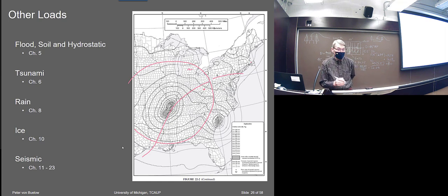Anyway, there probably wasn't a lot, and what there was, well, it would have been newer. Now I know, like where I live in Dexter, it's all masonry. It's all unreinforced masonry, and it's all like 150-year-old unreinforced masonry. So that you can almost kind of chip the mortar out with your finger. Some of it's been tuck pointed and repaired, okay, but it's still probably not in the strongest condition.